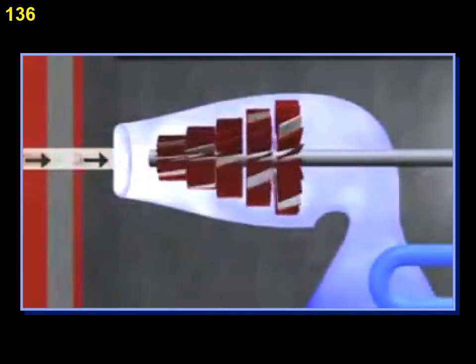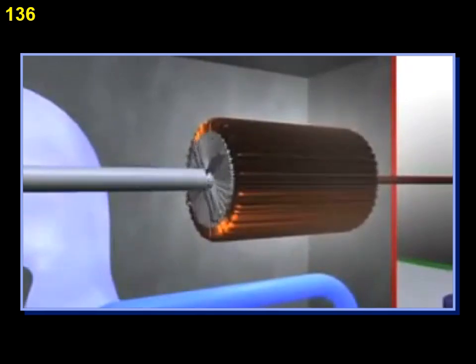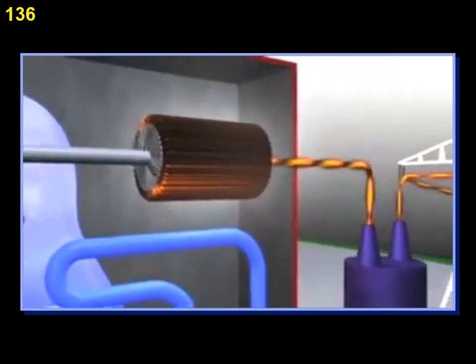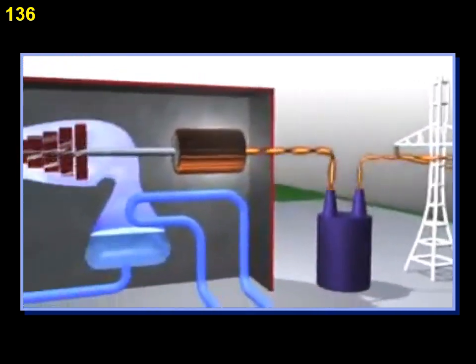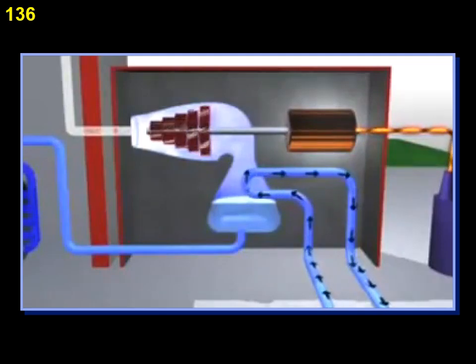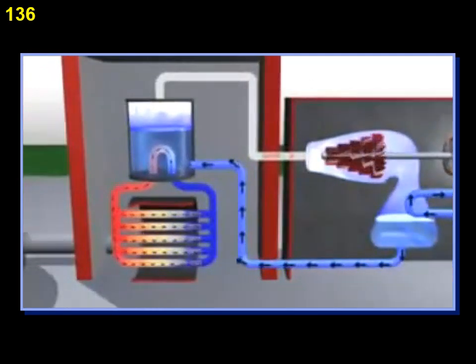and turns the shaft connected to a rotor in the generator, causing the rotor to spin. The spinning rotor is a large electromagnet that produces a rotating magnetic field. This field moves across coils of copper wire in the generator stator, producing electricity that can be sent across transmission lines. The steam coming out of the turbine is condensed back into water using cooling water from the lake and pumped back to the boilers to continue the process.